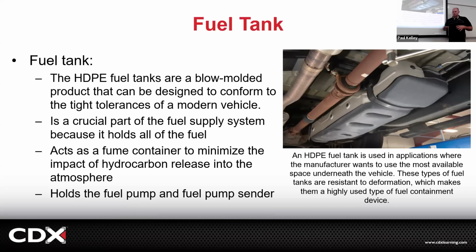So the fuel tank's job is not only to hold the liquid fuel, the go-go juice, but also to store the vapor and be sealed. However, we need a way to vent new air in as the fuel level goes down. So we're going to have this whole evaporative emission system, but these tanks are actually really good at containing those hydrocarbons. That's why you need to have the gas cap on. If you leave your gas cap off, what happens?